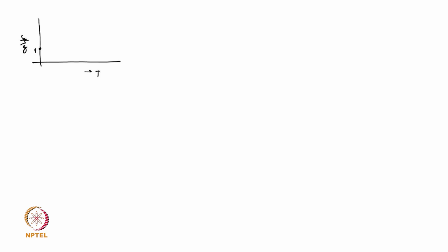And that point is known by two names. PGA, that is good. And another name? ZPA. Yeah. So one is the PGA, peak ground acceleration, and another is the ZPA, zero period acceleration. Good. Then it goes like this. So what is that time period here? 0.1 second. Industry people will just remember it all the time when they are doing that. Then it will go. Okay.